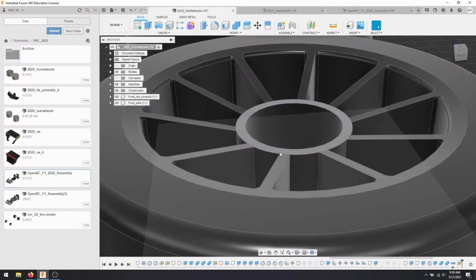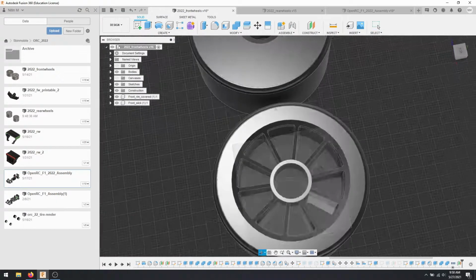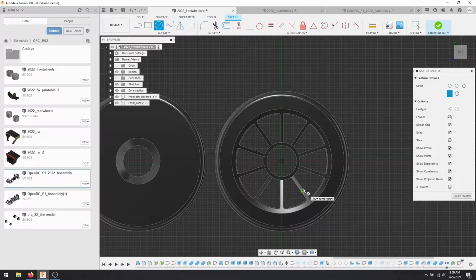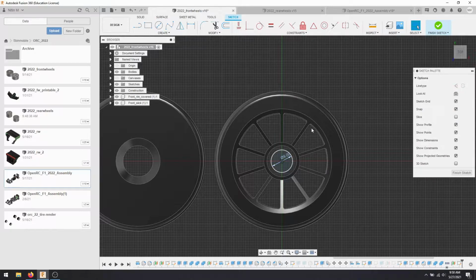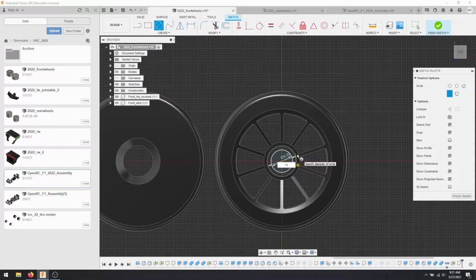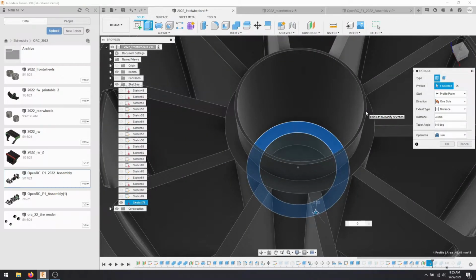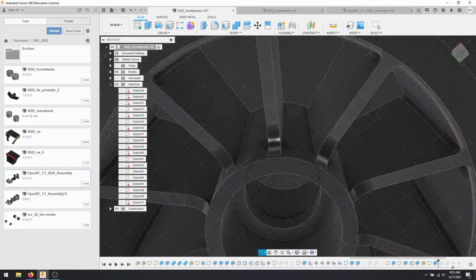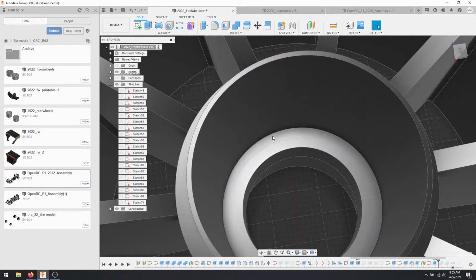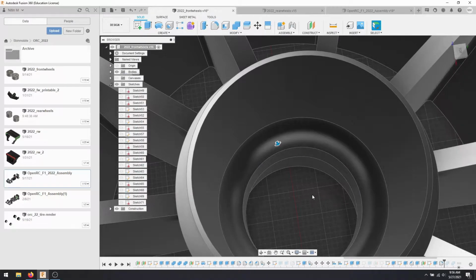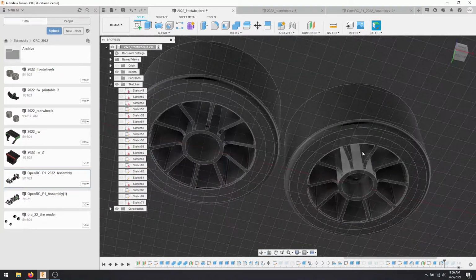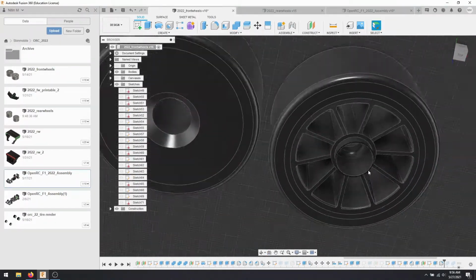I added that and also reduced the bearing slot diameter to check if the earlier fit was correct. And it turns out the earlier bearing fit was spot on, and the new construction also did the job of keeping the wheel nut separate and the wheel in. I corrected the bearing slot diameter and also reprofiled the rim cut angle because I want to be able to fit the original front axle, which was designed for a much thinner wheel, and also it looks really good.